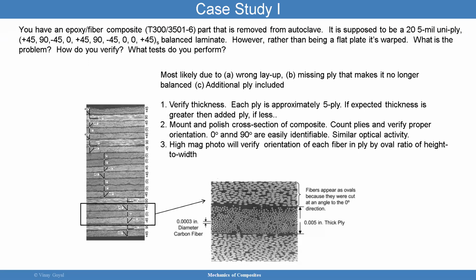So certain products can be purchased from different places. The bottom line is that the 35016, which you're seeing there, is really a high strength, damage resistant structural epoxy matrix. That's why it's so nice, because it's an epoxy resin system that can be used with unidirectional or even woven composites. But the nice thing about 35016 is that it was developed to operate in an environment up to 300 degrees F, which is really nice because you may have a lot of applications where composites could be exposed to high